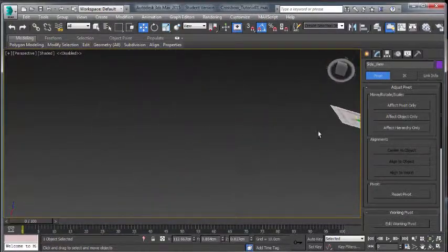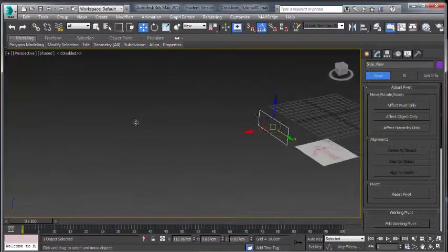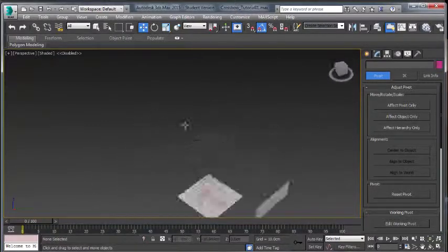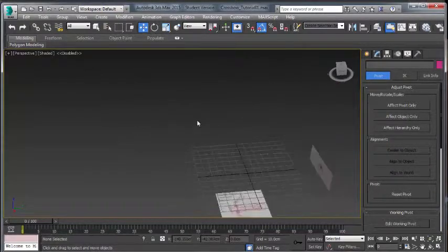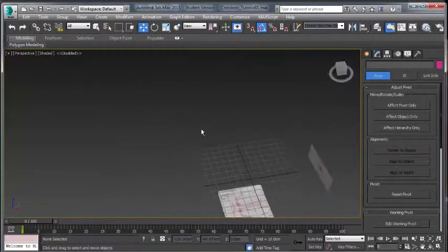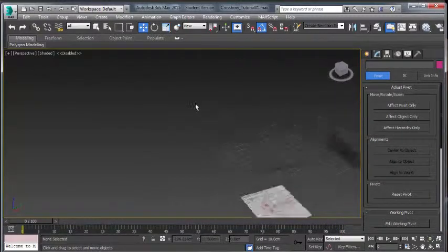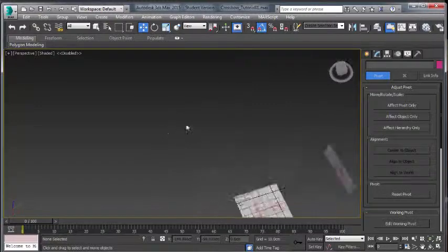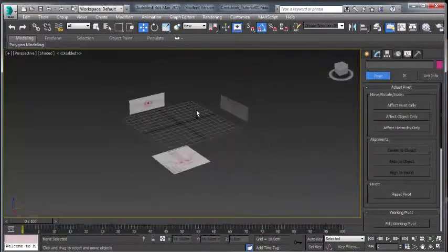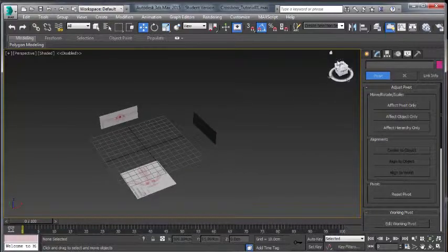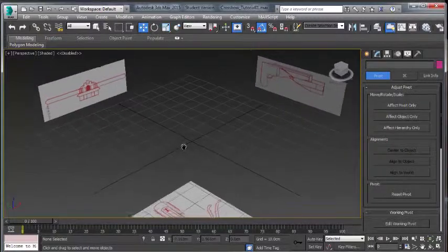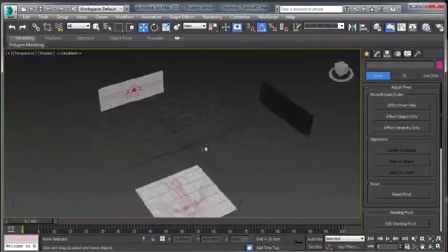Perspective. I'll just also too, if your canvas rotates very strangely around your viewport, this is because you have either selected something that doesn't exist anymore, or you've deselected something and it's just rotating. It's trying to rotate around your entire scene. So to change that, or if it's rotating very strangely, simply go to the view cube just in the top corner of your viewport, and that little house icon that appears, just click on that and it'll reset the rotation and your camera view to the center of the world again.